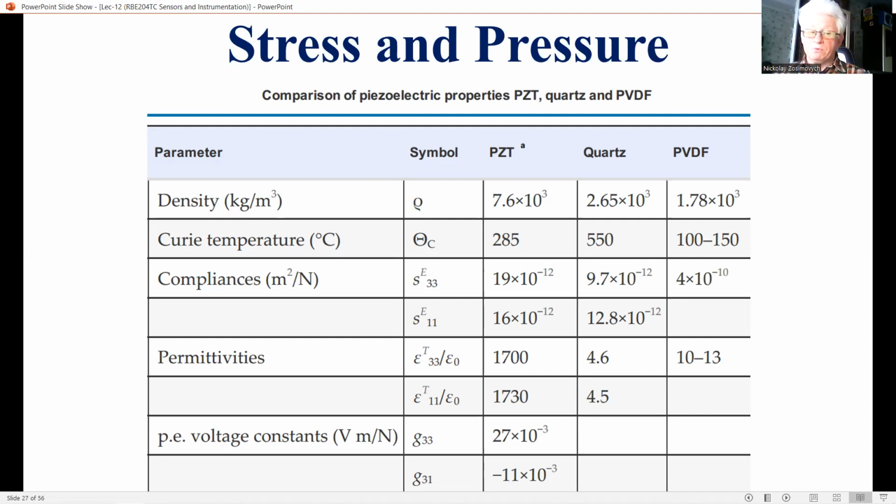Many properties of the prototype have been determined experimentally: sensitivity to temperature and humidity, response time less than 100 microseconds, frequency range and stability over time, like aging and creep, as outlined in the preceding section. The sensor element is also pyroelectric, so it responds to temperature changes as well, and shows a high pass characteristic that depends on the temperature-dependent loss factor or resistance of the membrane.